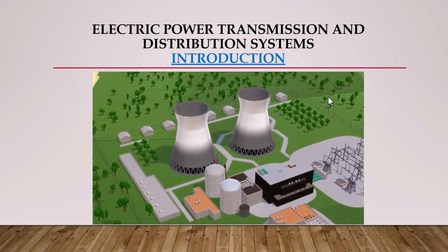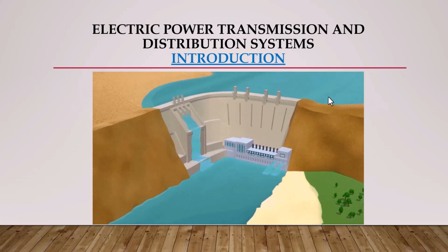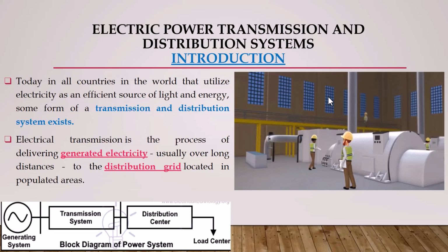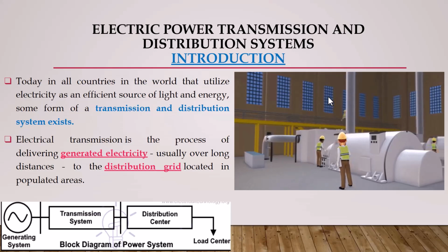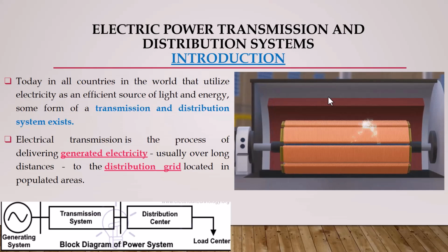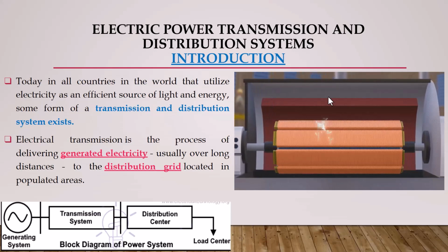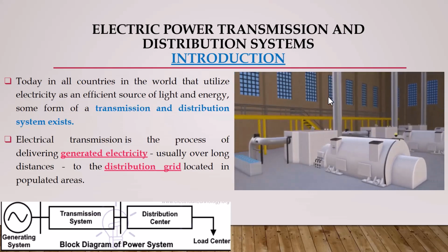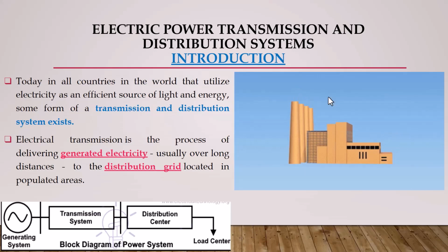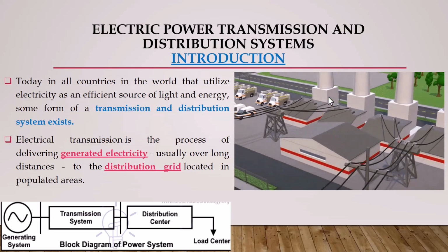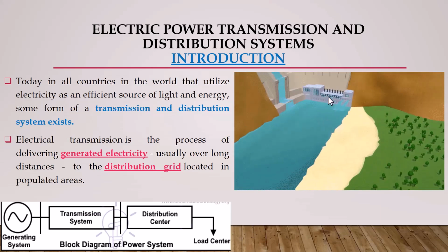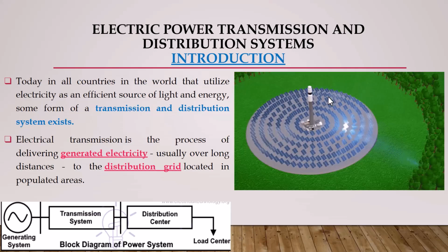In the structure of electric power supply, once electricity has been transmitted over long distance at very high voltage like 132, 66 kV or 33 kV, it needs to be stepped down to more manageable levels for practical use. And this is where primary and secondary distribution come into play. At the primary distribution stage, the transmission voltage is reduced to 11 kV at a substation using step-down transformers.